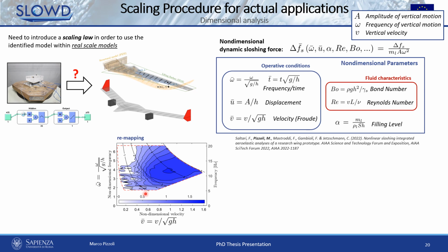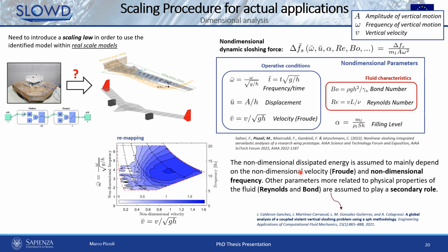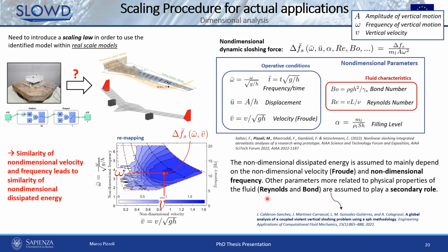that we defined, that assumes that the dissipated energy depends exclusively on these two operational parameters, the velocity and the frequency, with the assumption that the parameters related to the physical characteristics of the fluid, so Bond and Reynolds, play a secondary role. However, this assumption is partially supported by numerical studies presented in some papers published by partners in the SLOD project. And then the scaling law is defined in this way.